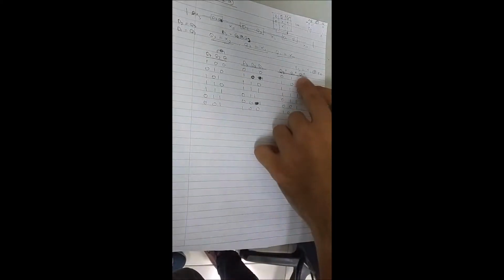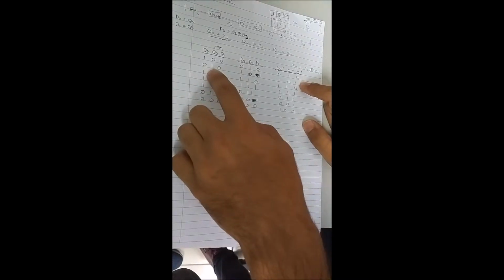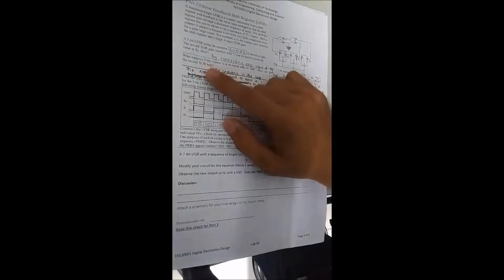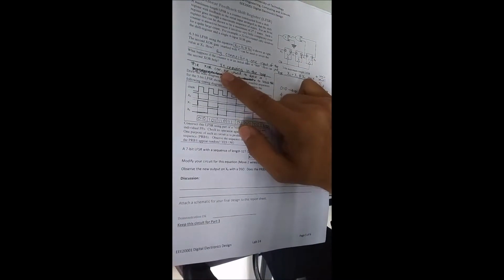And the previous state is the same as the next state. As you can see here, 0, 1, 0 is the same as the previous state for this one, 0, 1, 0. And the same goes on for every other truth table. And as you can see here, we got this based on the timing diagram here. And the question asks us, what happens if the counter is in an initial state of 0, 0, 0? How can the second XOR help? It remains in the loop, and the XOR can be used to force a 1 to break this loop over here. Let's move on to the circuit.